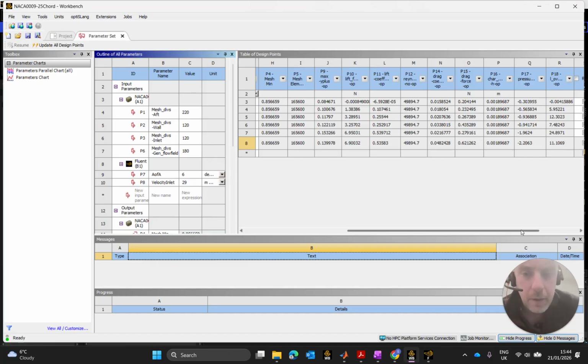So yeah, it's probably down to the fact that this is being done as a steady analysis, where a transient analysis would have delivered much more reliable and definitely much more stable results. Remarkably, in instability within the flow comes stability in results, providing you're on the right solver.